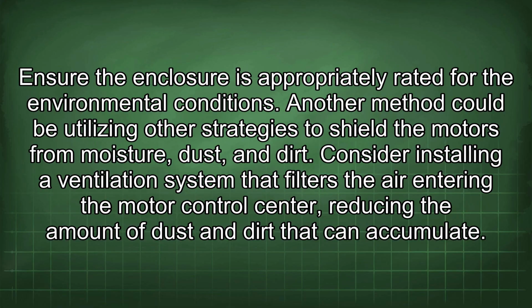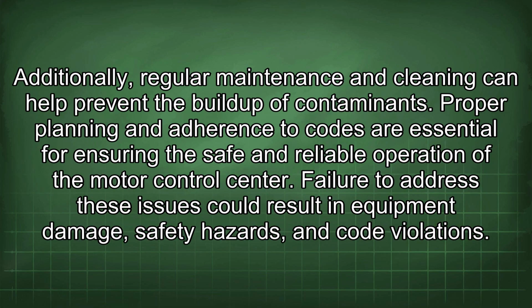Another method could be utilizing other strategies to shield the motors from moisture, dust, and dirt. Consider installing a ventilation system that filters the air entering the motor control center, reducing the amount of dust and dirt that can accumulate. Additionally, regular maintenance and cleaning can help prevent the buildup of contaminants.